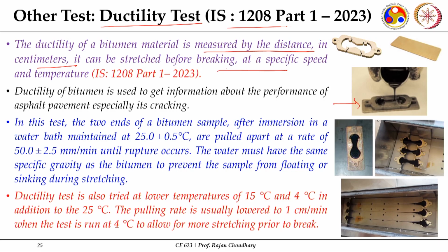Standard dimensions are given in IS 1208 Part 1, and you stretch it in a water bath. Why? To maintain a standard temperature, it is kept in a water bath and stretched. Here both the ends are getting stretched, and you stretch it at a standard rate. It says 5 centimeter per minute. So, you stretch it at a standard rate.